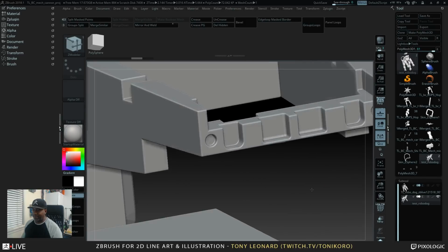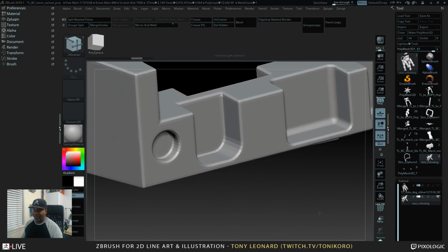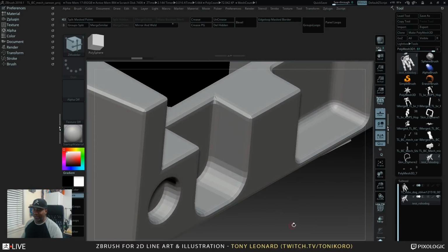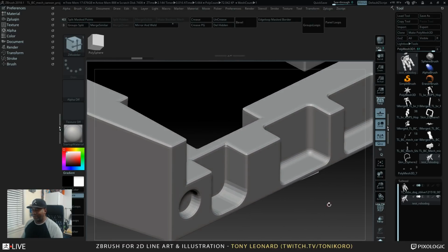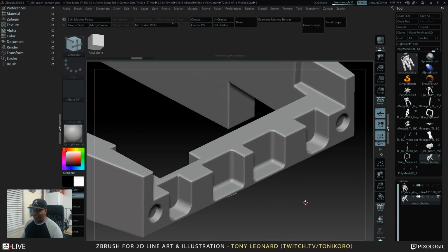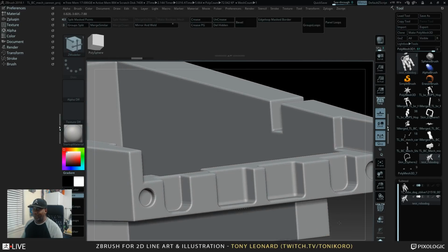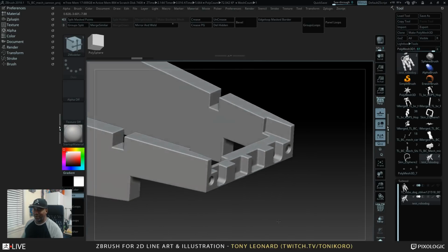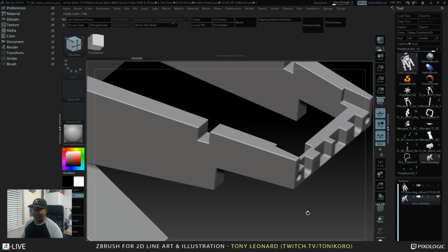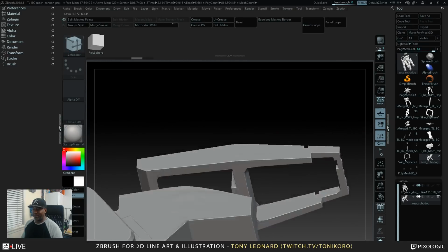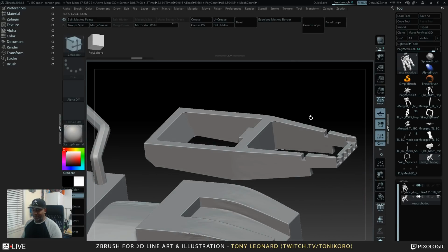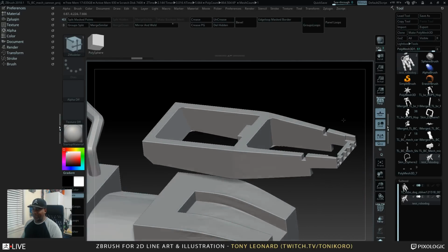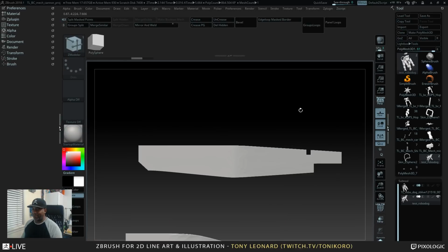Oops. And they look pretty clean. Some of the beveling worked out pretty nice. If you look very closely, you can see the beveling and how it comes out. Depending on how you clean it up, it might show you some nice geo, but if it doesn't have the supporting edge loops, it's probably not going to work out too good with stuff that's triangulated, because it breaks some areas down, and you get faces that are kind of overlapping. So if the bevel was turned up a little bit cleaner, maybe more than 3 or something like that, you could probably start to see it.